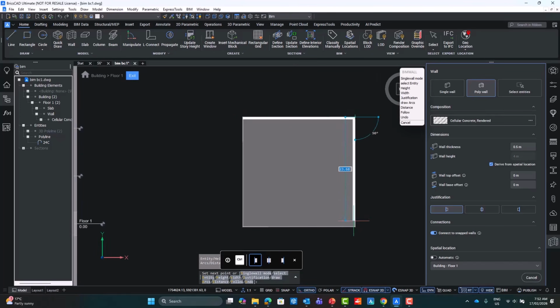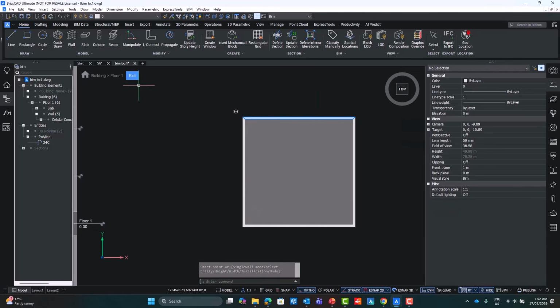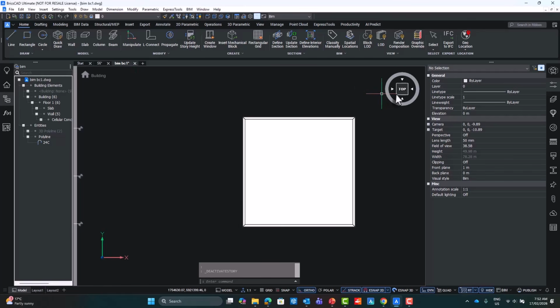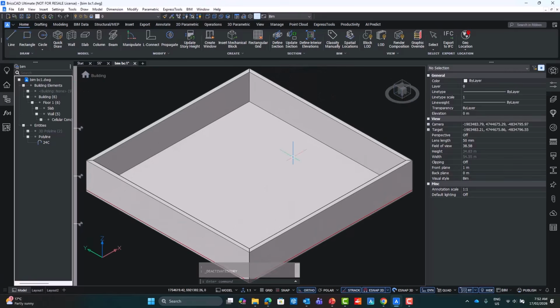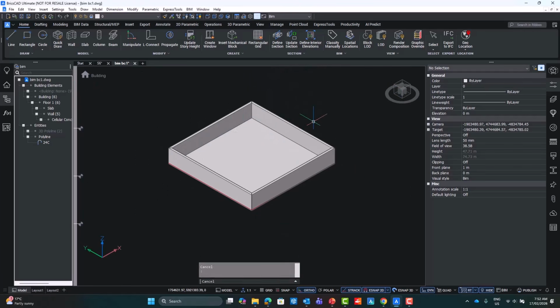So I'm just using some reinforced concrete here. We can adjust this and make this more thick as needed. Just using simple snapping tools will allow you to generate that wall. And then finally, we want to add some piling.